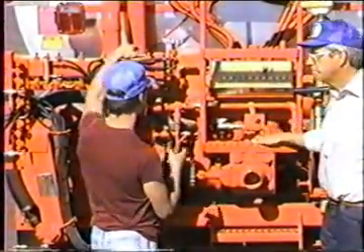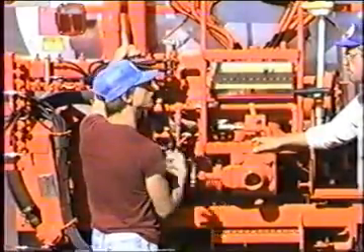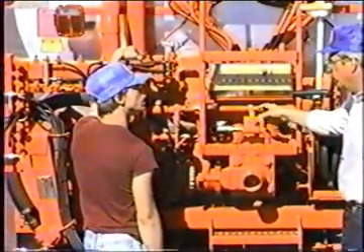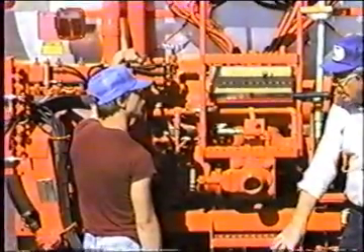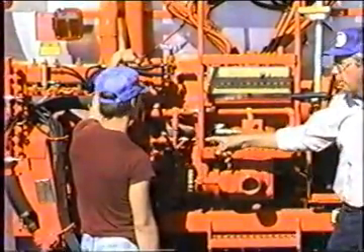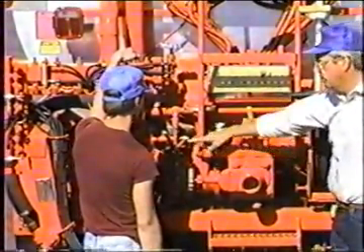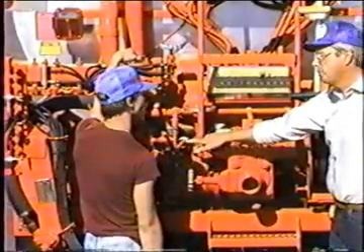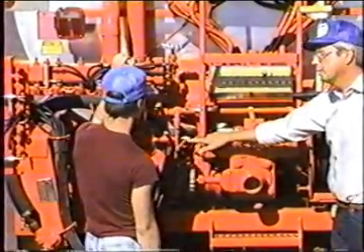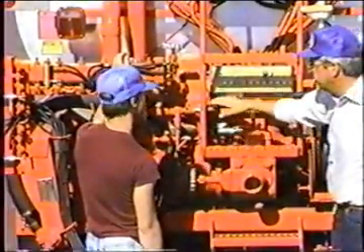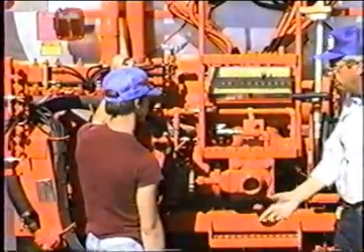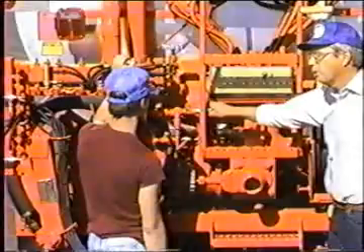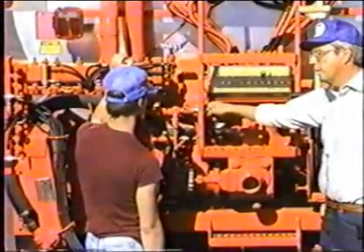You don't have to worry about asphalt plugging up your pump, or only in the situation that we were going to run asphalt out of the tank and not use this pump. All the other times we're going to be using this pump, so we're going to clean that pump out anyway when we get done. So that's what I'm saying. In those situations where you're going to use a different pump or gravity off, then you would close this valve down to keep asphalt out of that pump.